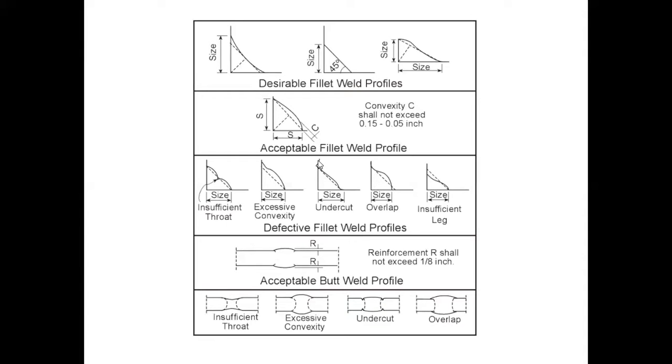Here we can see we got that undercut, kind of an example off of this one. Now maybe that long arc length, they cut away all this material. The weld is the correct size, but we got a bunch of undercut right here, and that would crack right from that point through whatever piece it was, and that would be a horrible weld failure.